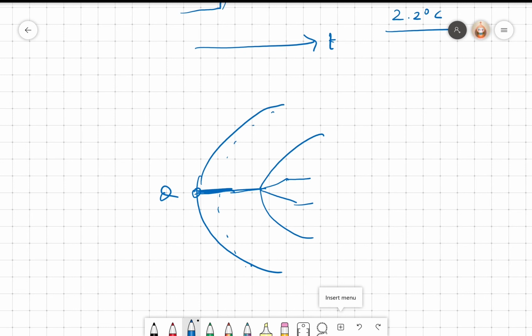As the layer keeps varying, new junctions get formed, and you still have the thermocouple in action. This is another advantage of a thermocouple. As long as the junction is formed and the junction is at a particular temperature, you get your thermo EMF of EAB.